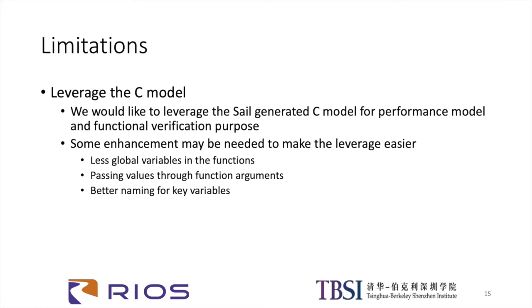As mentioned before, we treat the Sail generated C model as the only golden reference, and we would like to leverage the C model and integrate it into our performance model and functional verification test bench. We have integrated with the existing C model, and we believe some enhancements might be needed to make the integration easier, such as not using global variables in the functions, passing values or pointers through function arguments instead of accessing register file or memory directly inside the functions, and maybe naming some key variables instead of auto-generating names for better understanding.